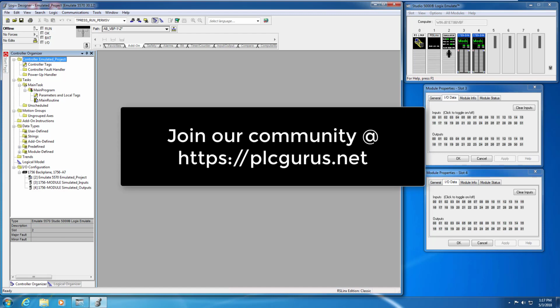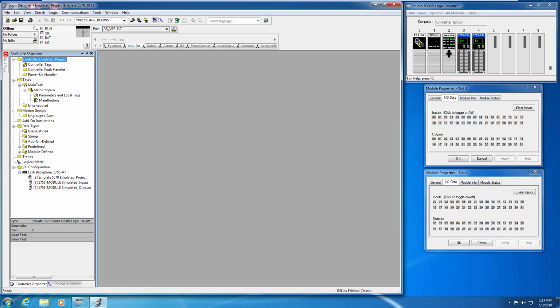So this is going to be another installment in our Studio 5000 Essentials video series that hopefully you've been following along with. And what I wanted to cover today is how we can go about creating, importing, and using Studio 5000 add-on instructions, or AOIs for short.